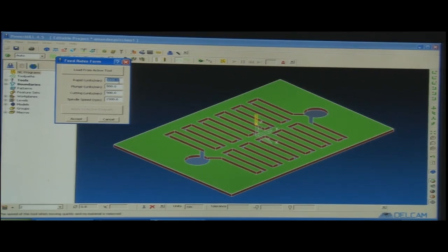Rapid mode is when the tool is coming from a far distance close to the workpiece. Anyway, when we talk about machining, the economics of machining also comes into play. The number one factor is quality. The quality has to be there, which is why there is a rough cut. After the rough cut, we do the major cuts, known as the finishing cuts. So, there are rough cuts, then rastering, then finishing cuts. The economics of machining is also there. We cannot put more time into machining whatever could be done in less time. We always have to optimize the machining time.